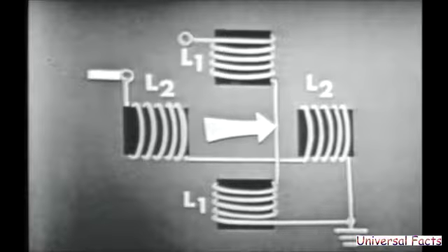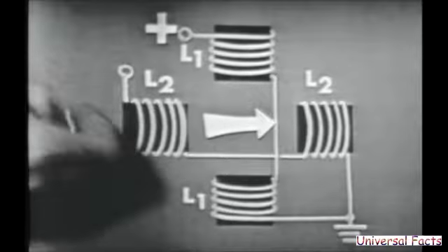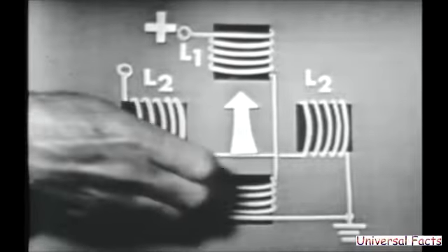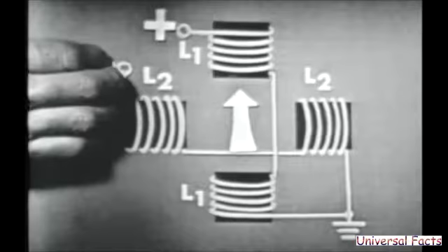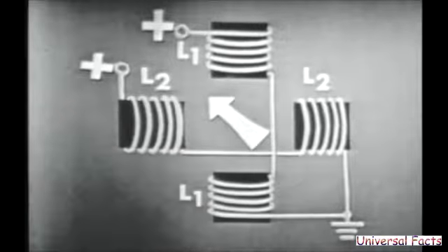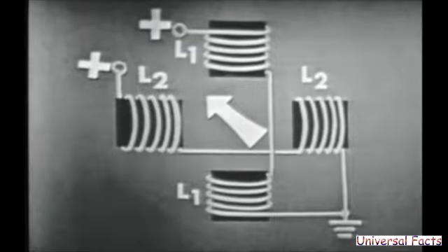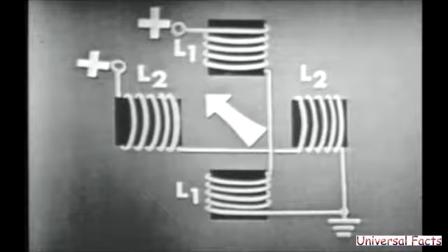And we can also energize both coils at the same time and produce four more directions. Okay, we're going to pause there. Now, by supplying both L1 and L2 with this polarity, L1 produces an up direction, L2 produces a left direction, so the two equal fields combine and move up and left at this angle.